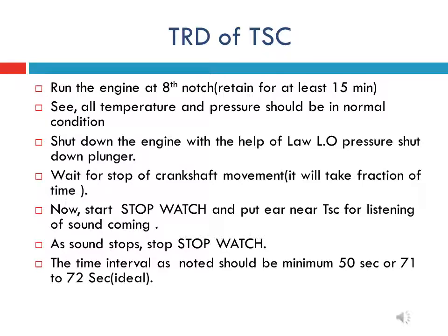TRD of turbo supercharger. Turbo rundown of the HHP turbo supercharger is to be carried out for checking the working condition of the rotor bearing and clutch performance. It is usually carried out when the engine is running on full load. The procedure may be read here in this slide. The TRD should be 50 seconds to 72 seconds.